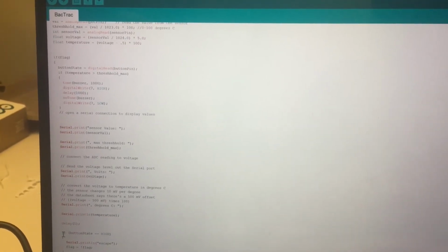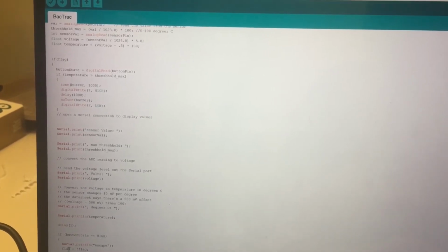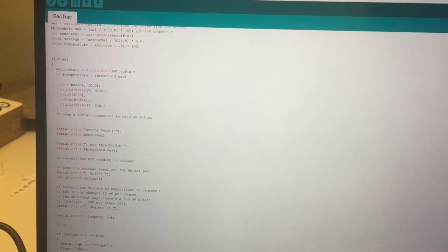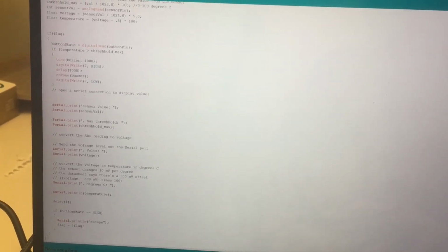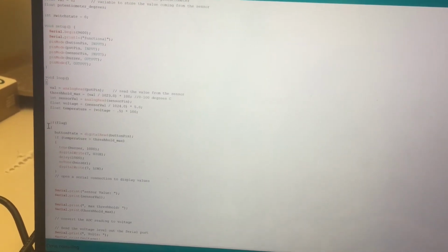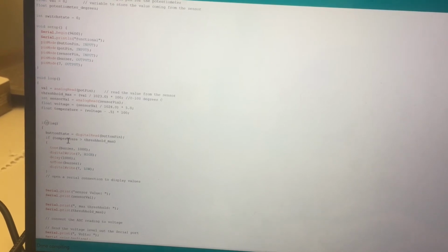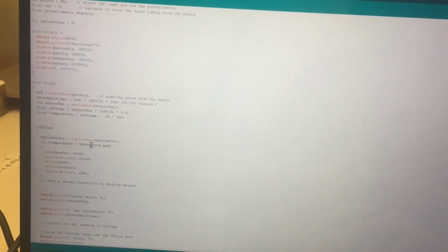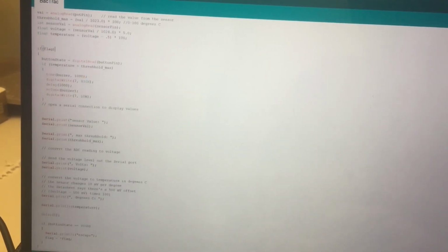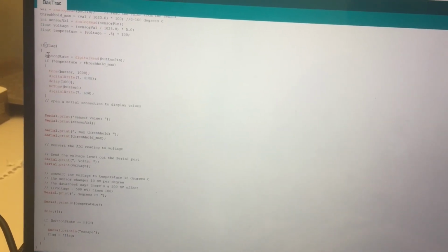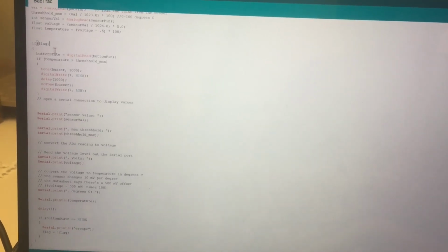Then over here, if you press the button, we print escape to let us know that we're ending the program, and that flag changes to not flag, which basically means we go from true to not true. This matters because over here, this breaks us out of this statement. So we stop checking the temperature, and we stop updating threshold max, and we stop all alarms. This basically ends the program until you use reset, which resets the value of flag to true, allowing everything to run once more. This works like a real alarm clock.